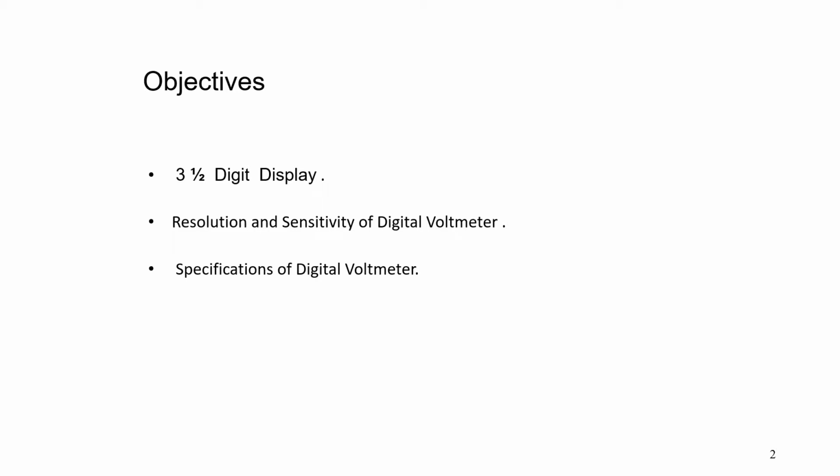If the input voltage is greater than the converter reference voltage, the comparator produces an output that causes the control register to retain 1 in its MSB, and the converter continues to supply its reference voltage as half V. The ring counter then advances by 1 count, shifting a 1 into the second MSB of the control register, and its reading becomes 11000000.